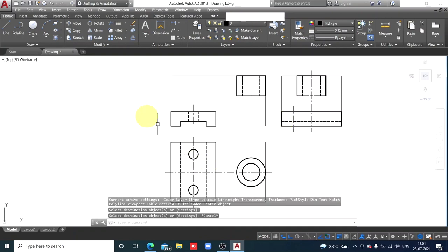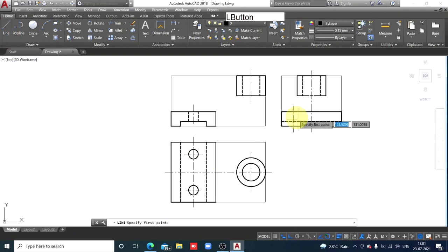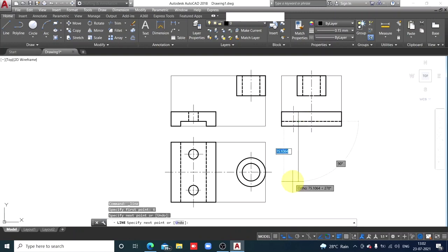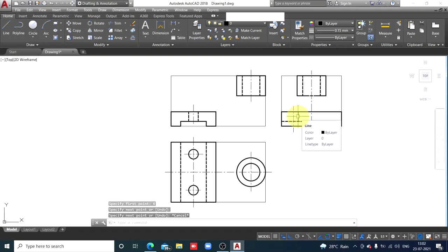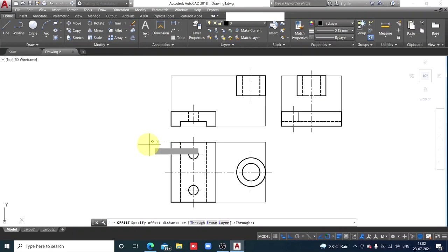And now we'll draw that hole. So from axis we should measure radius. On the right side is 6. Enter. So at the right side 6, I have drawn that. This is the line. I'll offset at distance, not through, but at distance 12 millimeters, because that is diameter.